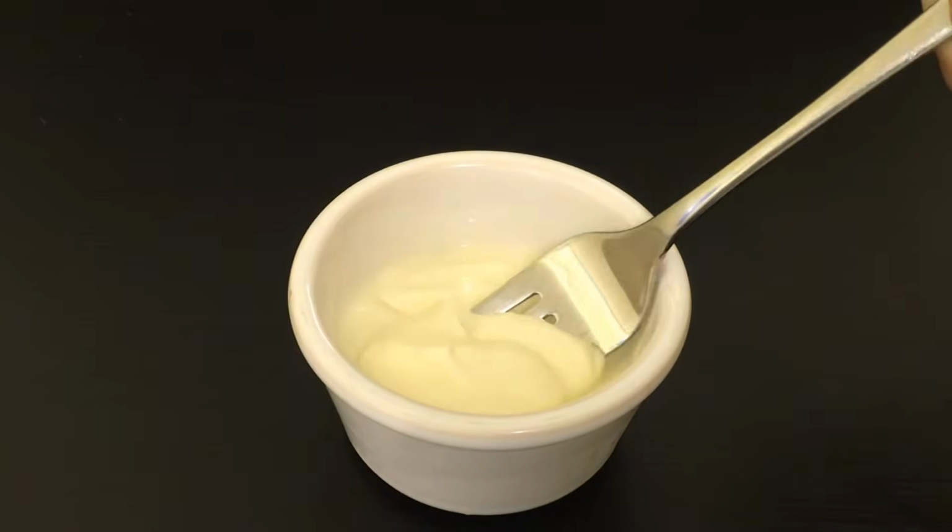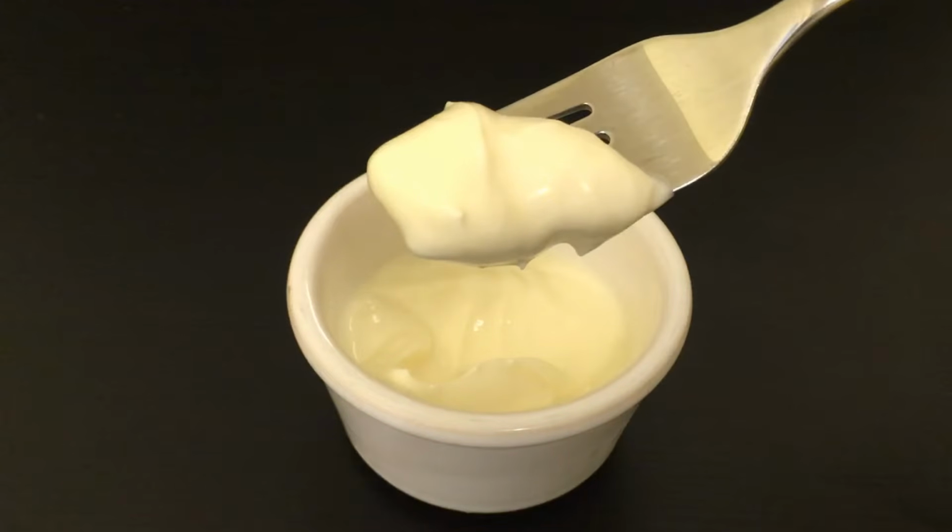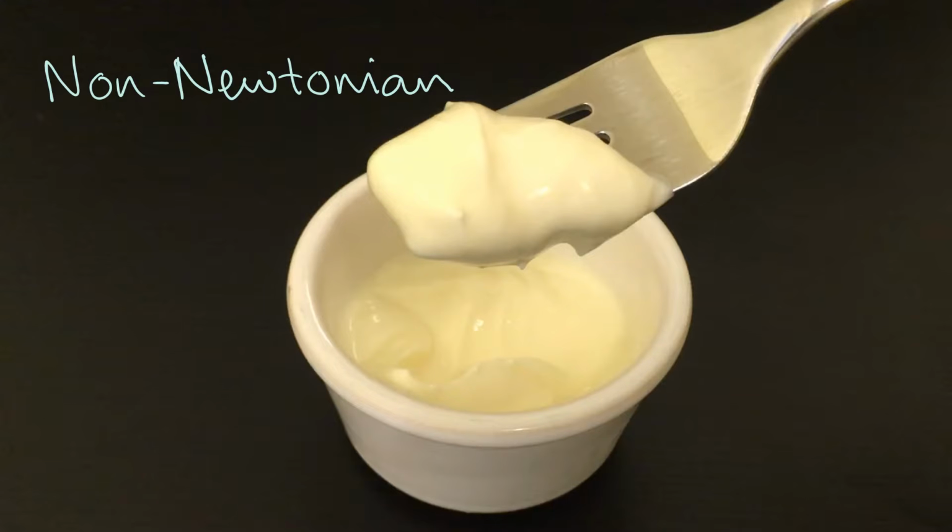But very often liquids don't have that ideal straight line relationship. Most thick fluids you encounter in real life are non-Newtonian. Fruit juices, smoothies, sauces, soups, salad dressings, toothpaste, paints, and cosmetics are all non-Newtonian. In all those cases, it's not a disadvantage, not at all. It makes the paint easier to control, it makes the dressing stick to the salad, and it means it's not a great deal of effort to drink a smoothie. But it does mean that we can't describe any of these liquids with one measurement of viscosity.